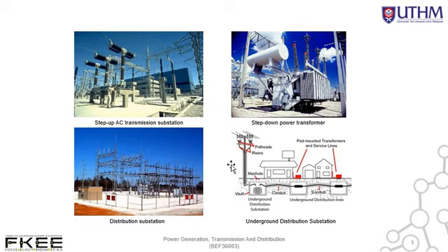Distribution substation and underground distribution substation are located near to the end user. Distribution substation transformer will step down the transmission or sub-transmission voltage to customer utilization voltage level, where the power is being distributed to industrial, commercial, and residential consumer.